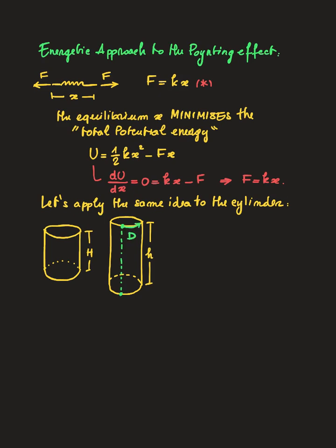Now, in this case, the class of deformation is defined by the following, and I will give you directly the result, but it's very easy to deduce it. So little r is equal to the square root of H over h, times capital R. Theta is equal to capital Theta plus d z, and the lowercase z is equal to h divided by capital H, times capital Z. Now, in this problem again, d is prescribed, d is given, just like in the previous case.